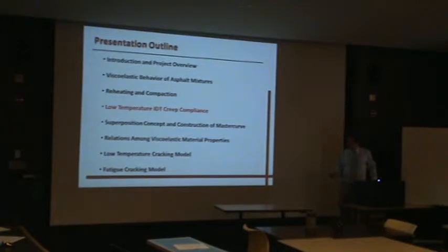After that, the first test I'm doing is the creep test, which I use the first specimen right here. So in the creep test, as I said, I will apply constant stress and I will read the strain, and I expect the strain to go up a little.